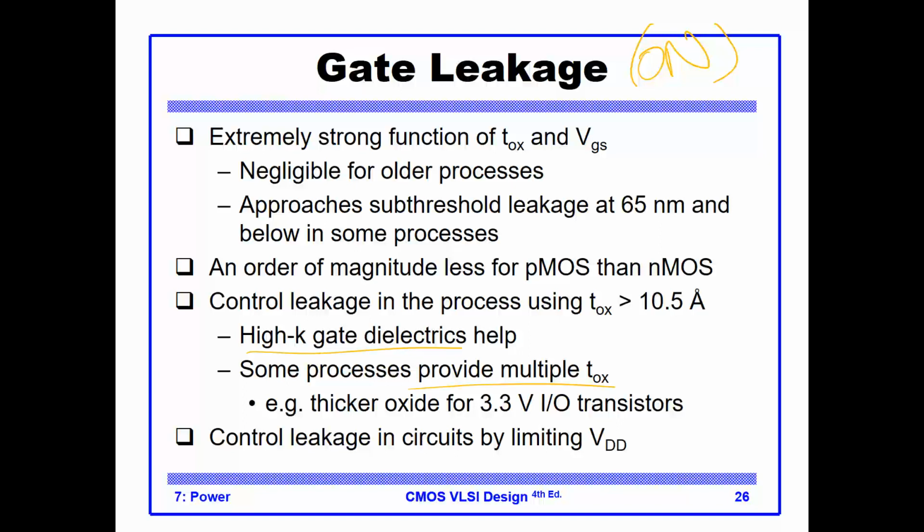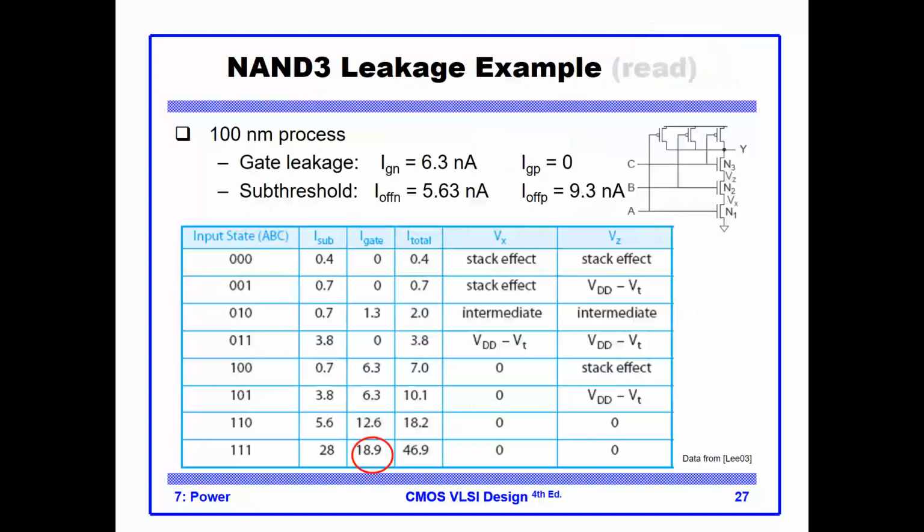And obviously, limiting VDD should reduce this leakage current, because these are electrons penetrating the insulating SiO2 and going to the gate. If you reduce VDD, you are reducing the vertical potential, which pulls those electrons from the channel all the way to the gate. So this is another reading material.